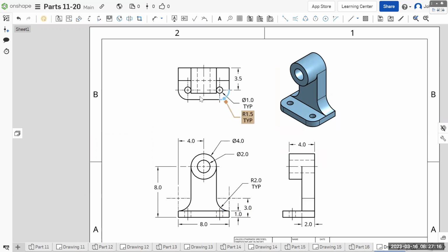You'd make these circles, which share the same center point, diameter 1, and go all the way through. Then you would make this footprint of the taller part, which is halfway between here and here, and this thickness, and extruded the height of this, or total height.